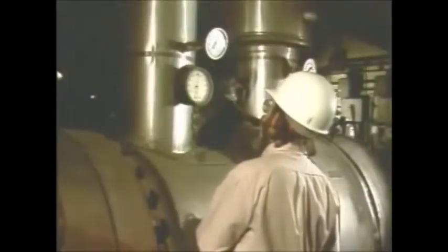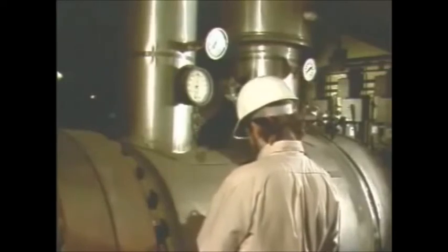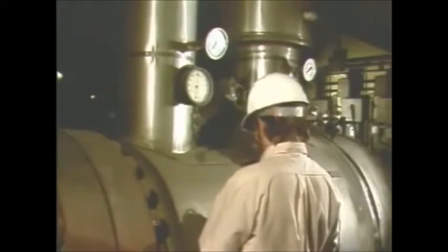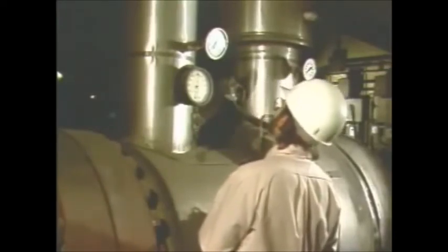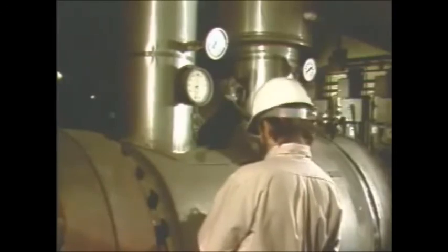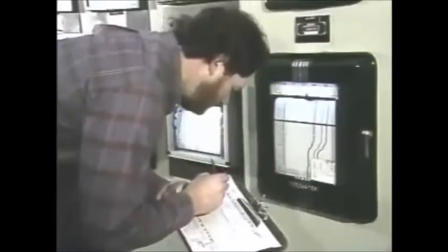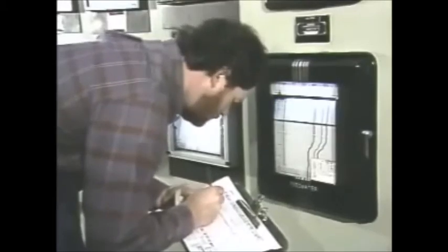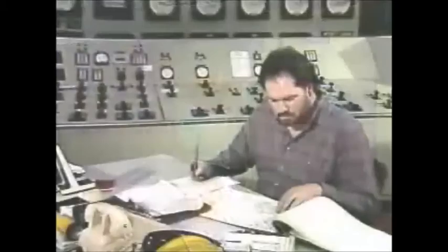Of course, operating with even a relatively small tube leak is inefficient, so it's important to find small leaks early and get them corrected. Small tube leaks may be difficult to detect, though, because they don't show up on instrumentation, but some small leaks may become noticeable when you calculate the TTD and the DCA for a heater.